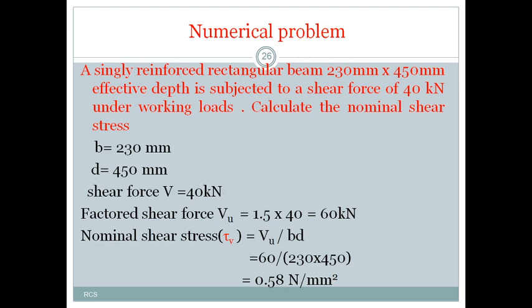Based on today's lecture, we will discuss a numerical problem, that is calculation of nominal shear stress. The problem is: a singly reinforced rectangular beam of 230 mm by 450 mm effective depth is subjected to a shear force of 40 kN under working loads. Calculate the nominal shear stress.